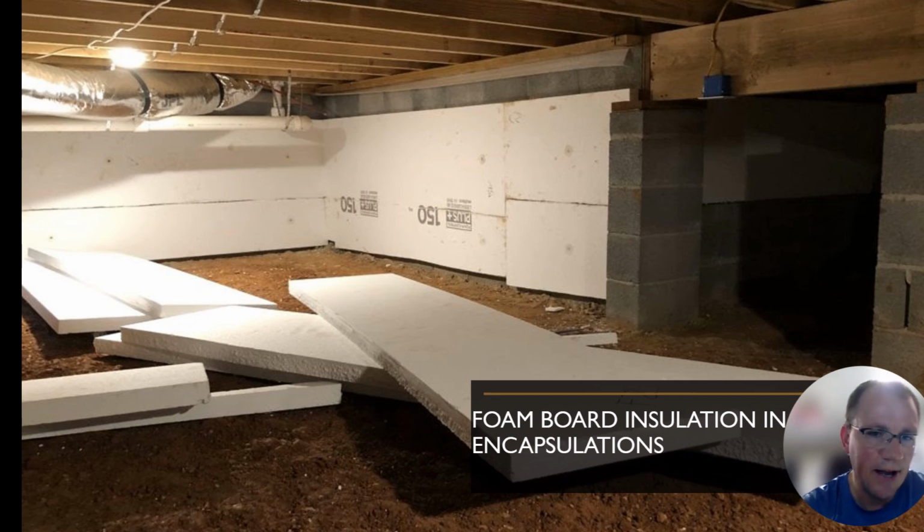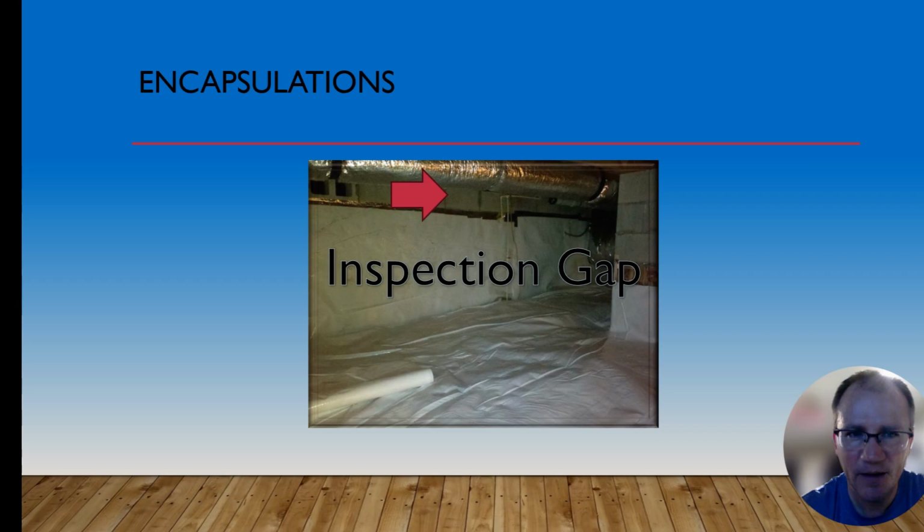Another thing you may look at is, do we need to do insulation? As you can imagine, under floor joist insulation has a lot of problems. It gets wet, it gets moldy, it falls down. Foam board insulation is a great idea. Just keep in mind you have to have your gap to do termite inspections. What you're seeing here is a 2-inch foam board insulation that we anchored with 22 caliber nail guns with washers on it. So I'm not going to talk a lot about that, but I did want to mention it because it's definitely a big part of crawl space inspections and especially encapsulations.